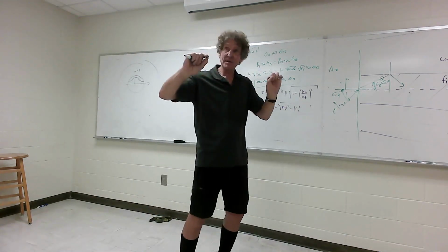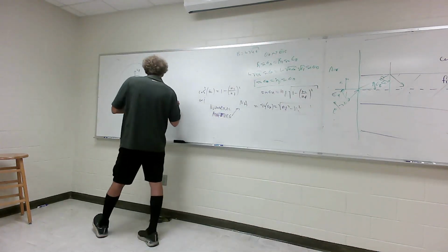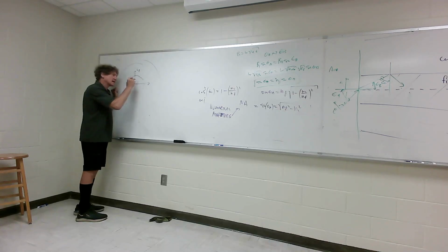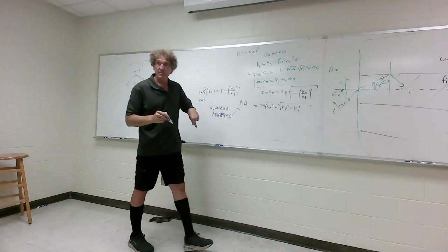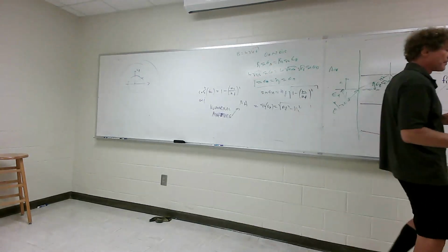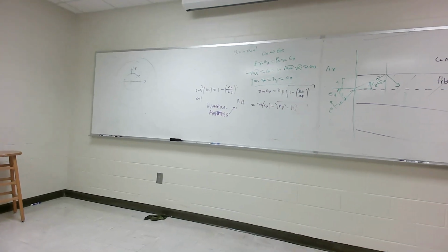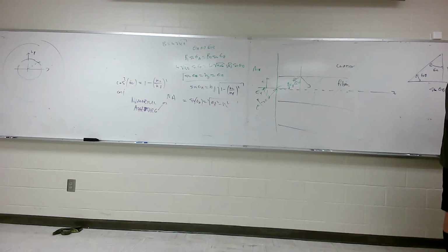Now it doesn't have the same index, the same intrinsic impedance. What they really do, they'll probably show something like this. It doesn't go from one value to the second. As you get closer to this point, it starts going from a high value to a low value, and there's a transitional point. So it isn't abrupt. It's called graded index fiber. And again, he doesn't even tell us what's so important about it. But the thing is, that's easier to make than step index. And it's used for multi-mode fibers.